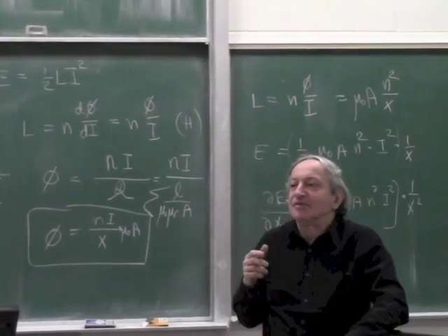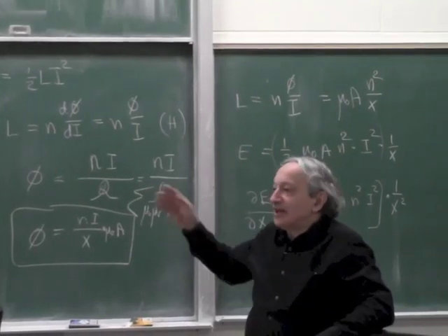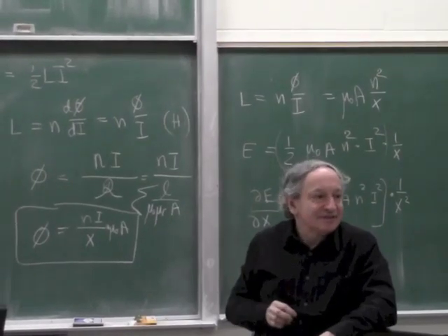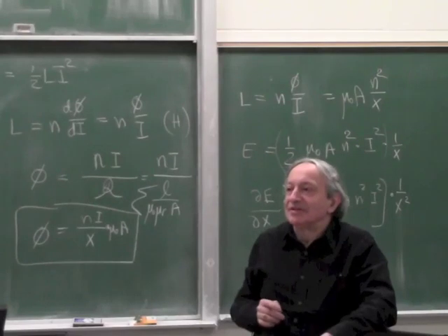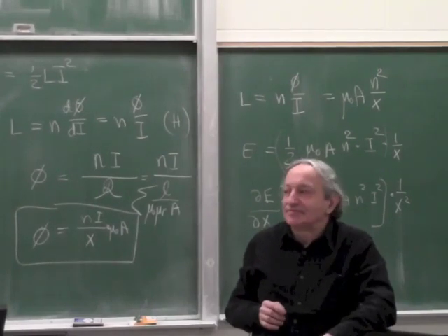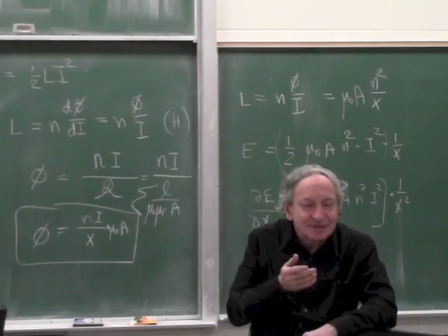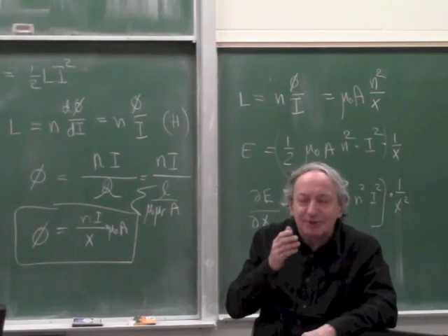So let's make the question a bit easier. What's so bad about variable gain in a servo system? Because if something is nonlinear with position, it's the same as variable gain. And that you should know. What's so bad about something with variable gain? Lead and lag is a constant. A little bit, but there's something much worse.